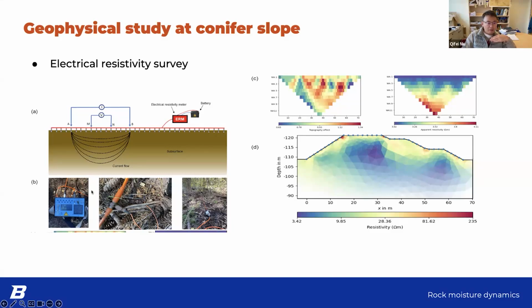Rather, there is a resistivity meter, and you can upload a sequence to ask the resistivity meter to take the measurements. Once you collect all the data, you can plot them as pseudo depths. That means you have data at different depths, but this is not the true resistivity. It is only a measurement, because, for example, the last data point is when you put A and B at both ends and M and N somewhere in between. It not only measures the deep soil, but also the shallow soil.